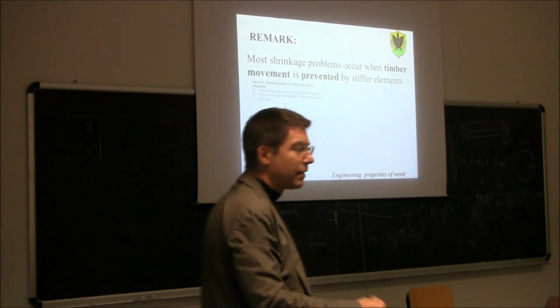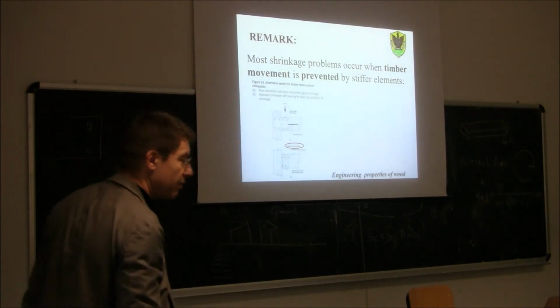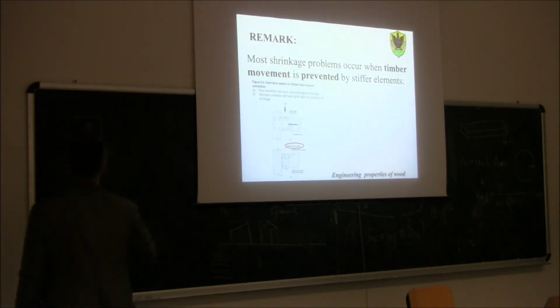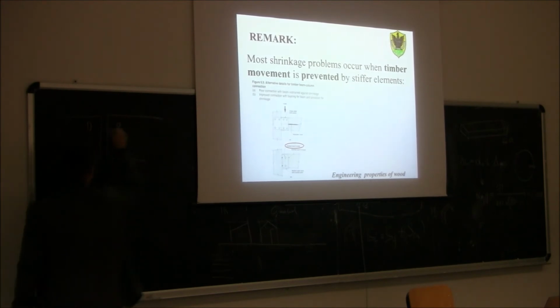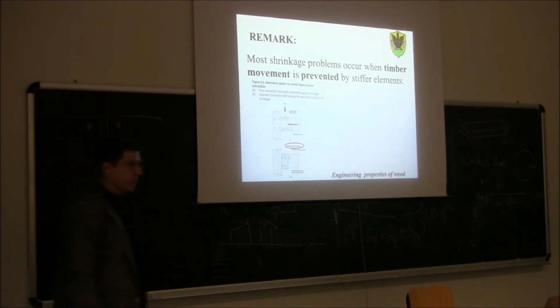We cut an elongated hole into the steel in such a way that when the wood is going to shrink, let's say this is the wood, for example, this is the hole, the bolts going through will be able to go down. Okay?